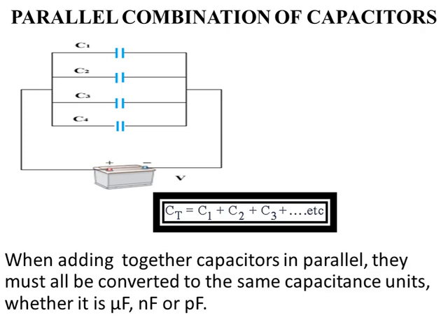So anywhere you see this type of connection, this is a parallel connection. These are parallel combinations of capacitances. When you need to get your equivalent capacitance, you just have to do C1 plus C2 plus C3 plus C4, and it gives you the total capacitance in that circuit.